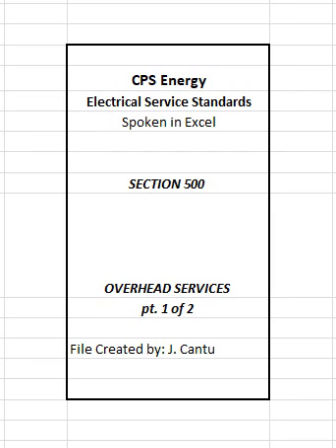501 Aesthetic design areas. In areas where overhead service drops are prohibited for aesthetic reasons, CPS Energy will supply with overhead to underground service laterals or from pad mount transformers. 501 Overhead to underground conversion areas. Overhead services are not available in areas that have been converted from overhead primary distribution to underground primary distribution. Only underground services will be allowed in these areas.